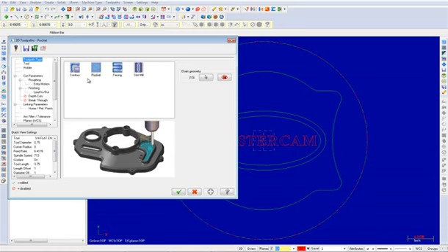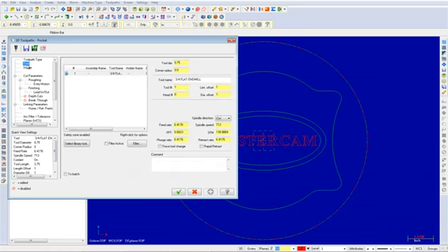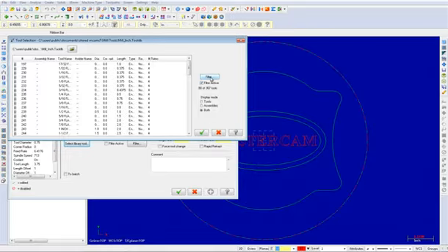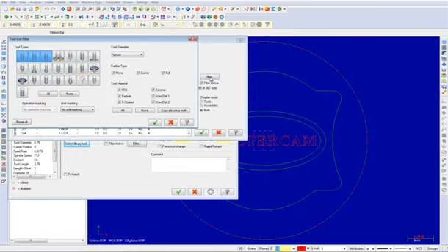From the Tree View list, select Tool. We will now choose a 1/8 flat end mill from the library and set the tool parameters. That being said, click on the Select Library Tool button and then choose the Filter button. Select the None button and then under Tool Types, choose the flat end mill icon as shown. Under Tool Diameter, pick Equal and input a value of 0.125.